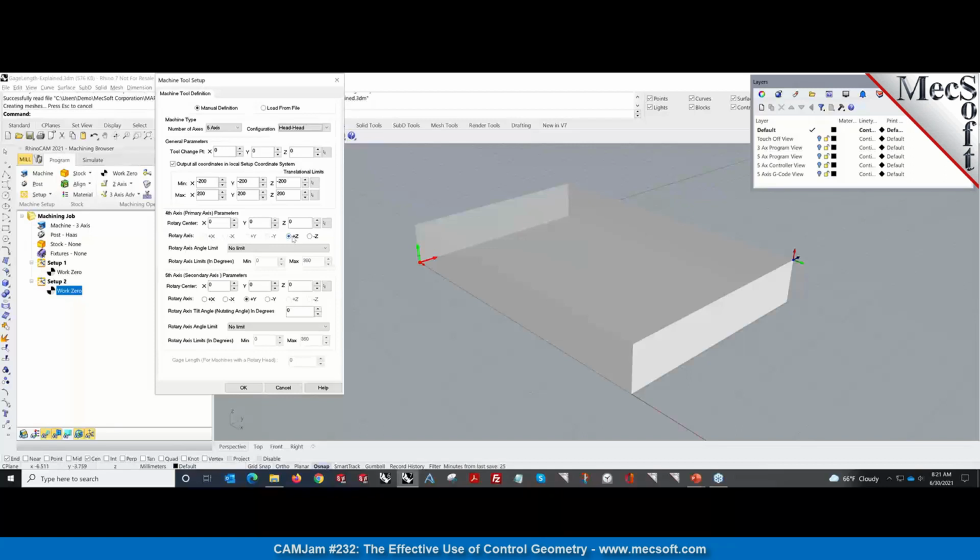Right now, when you select head, you only have these two combinations, either the plus Z or the minus Z. Those are the only two things you can select. And then for the fifth axis, you can select either X, positive Y, or negative Y. And then obviously, since you can't have both of these axes on the same coordinate axis, this is grayed out.